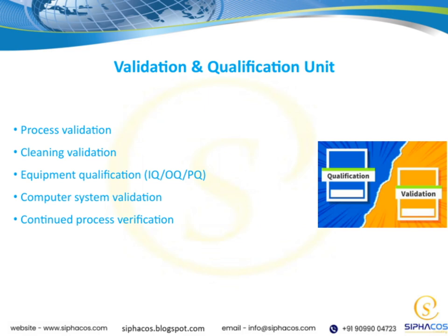IQ, or installation qualification, verifies that equipment is installed correctly and according to specifications. OQ, or operational qualification, tests that the equipment operates as intended across its entire range of functions. And PQ, or performance qualification, confirms that the equipment performs effectively in real-world, production-like conditions.